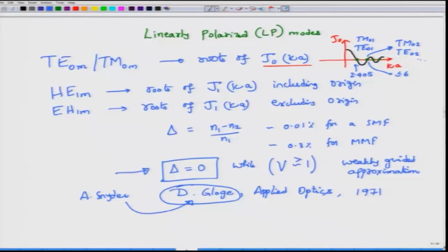Most of the times it is a curse, but with sophisticated signal processing algorithms, these different modes are now being used to increase the capacity of the optical network in something called mode division multiplexing. Anyway, these are topics that we are going to discuss later on during the course. So, it is good in some sense to work with many modes, but that many mode propagation is not for long distances. For long distances, you are mostly looking at a single mode operation.